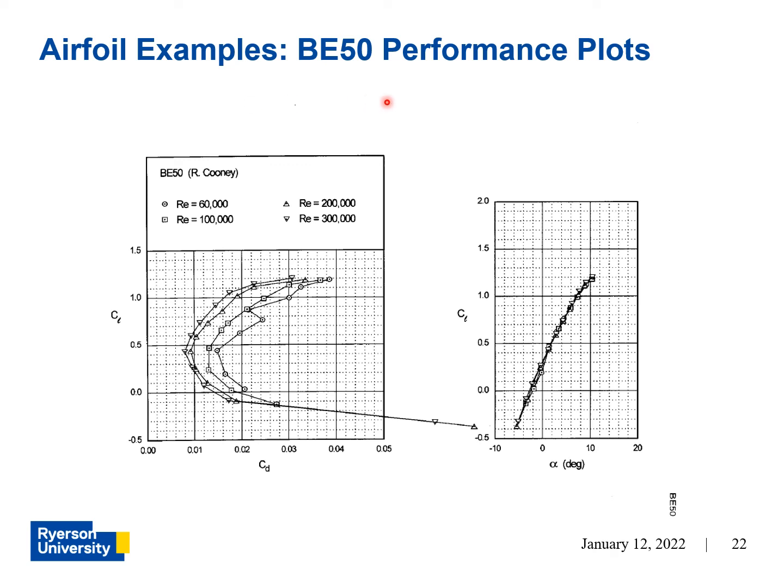So at mid-range values of lift, the drag is lower than the A18. And over the lift range of about 0.5 to 1, there's a smooth increase in drag, as you can see here. So this type of drag behavior, where the increase is smooth, is indicative of good glide performance over a broad range of aircraft speeds.